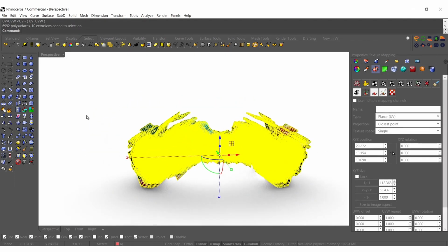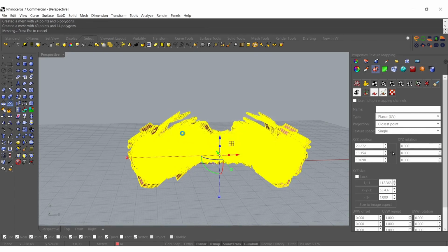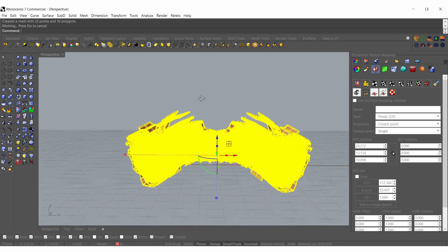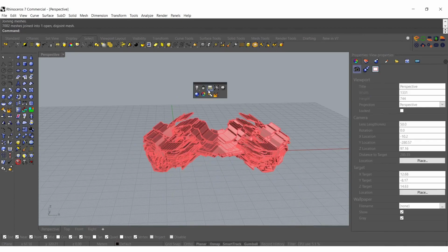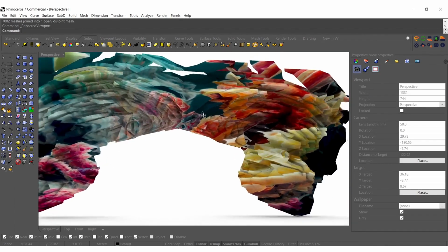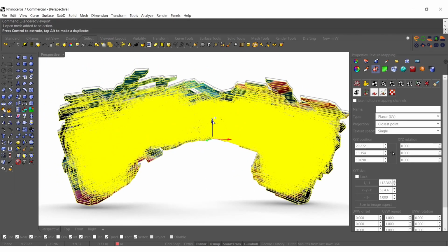And then from here, I'm just going to mesh everything out so it runs a little bit quicker. Since these are pretty simple shapes, it shouldn't take too long, and then I'm just going to join them together, keep our model relatively light. Still might mess with the texture map just a bit more. Just a moment to mesh. There we go. We can delete out our initial geometry, join this mesh together. It's looking decent.